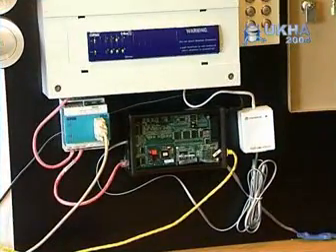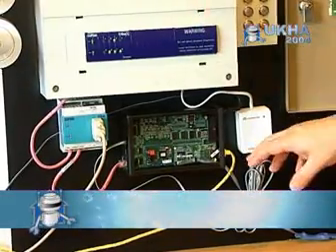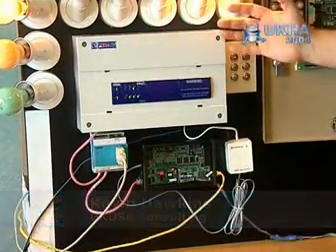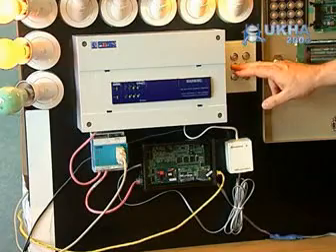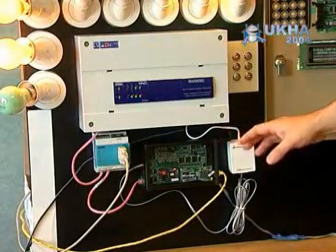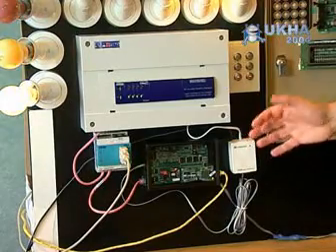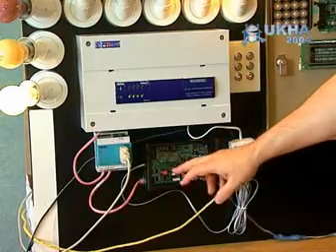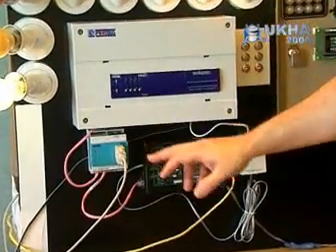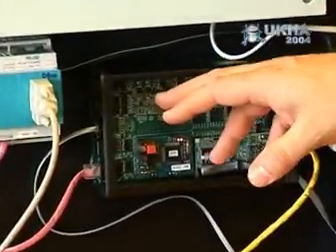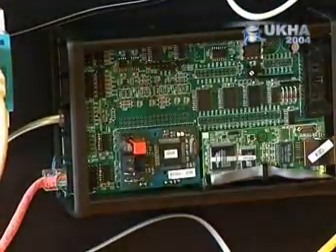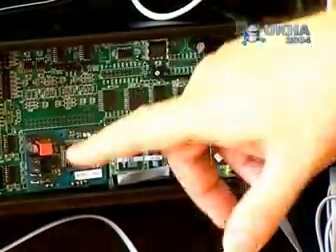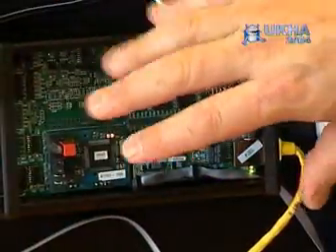What we created was a board to bridge C-Bus to Zap. So everything that happens on the C-Bus network, which is contained here, every lamp or switch change that happens is transferred to a Zap message that goes out and is used to trigger events on the Zap network, and anything that's a Zap message can be used to change the state of anything on the C-Bus network. We have a board that has 4 serial ports, one of which is dedicated to C-Bus, RS485, 422 and RS232, and potentially an X10 interface as well, and some parallel I/O. So straight out of C-Bus, straight into Zap, neat embedded standalone solution.